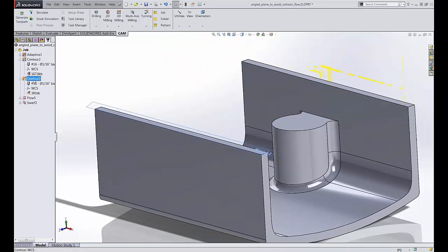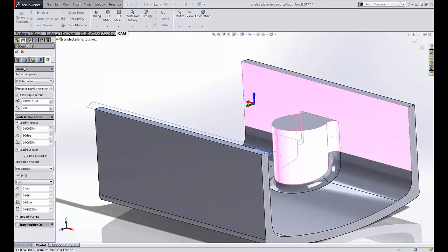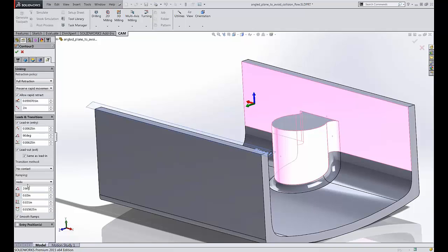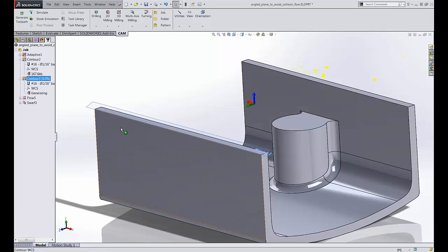So then what we can do is go into this one, which is the exact same toolpath, but it has multi-axis turned on. But what we want to do is use rest machining. Probably put a slightly smaller value in here. Same thing here. We'll turn on plunge. And this will just go up and clean up in the areas where you genuinely need the tilt, that are basically impossible to do with that tool without tilting. This will come in and get those spots.